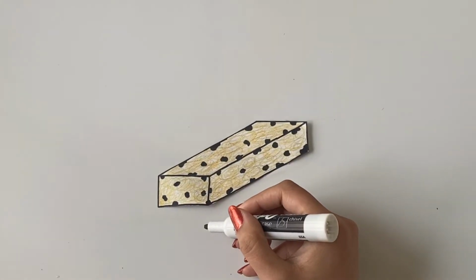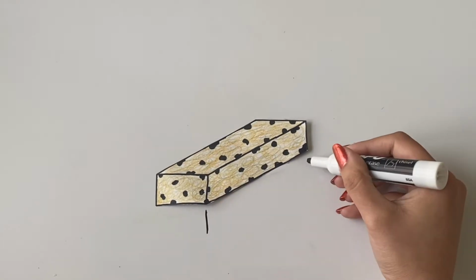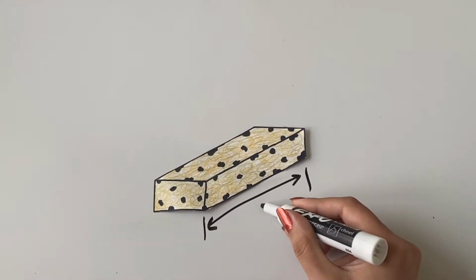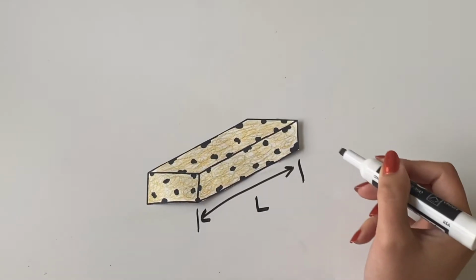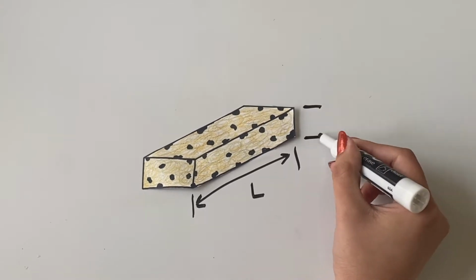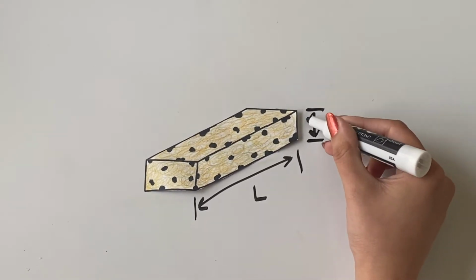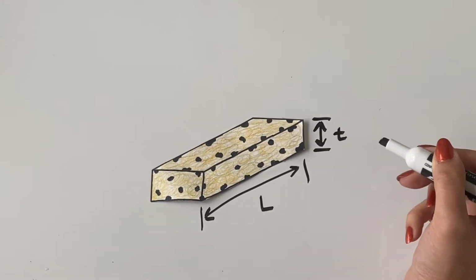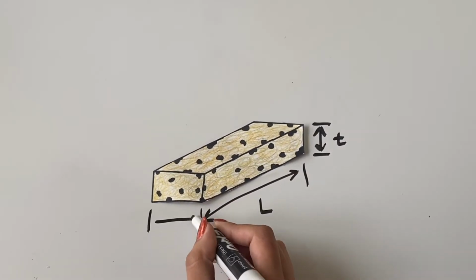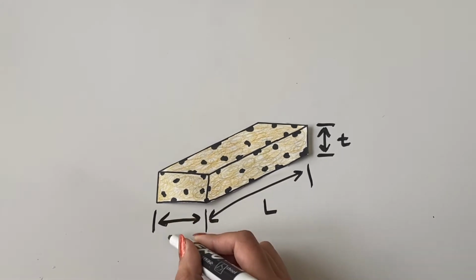There are 3 major dimensions that our processing line will conduct for the bar. The first is the length, which is dictated by the width of the pressing rolls and induced by the wedged middle lane guide. The second dimension is the thickness or the height of the bar, which is pressed down by those pressing rolls. And then the final dimension is the width, which is induced by the bar cutter.